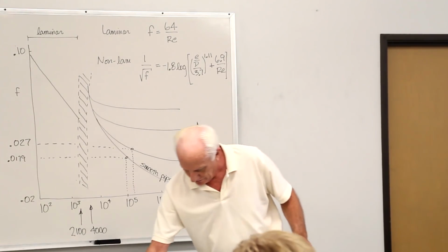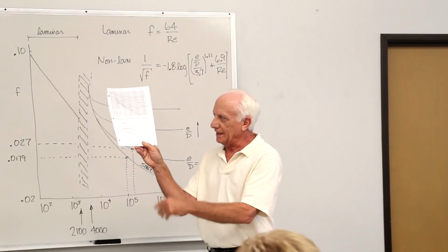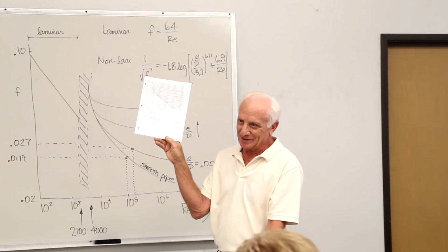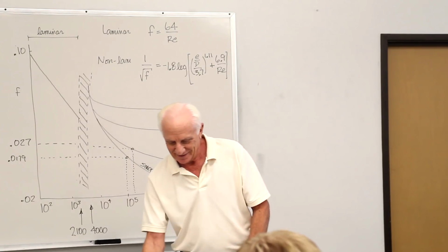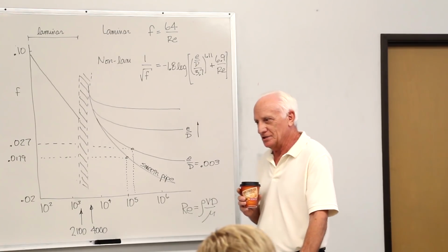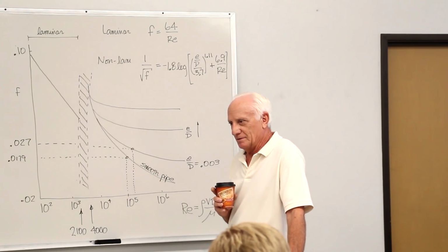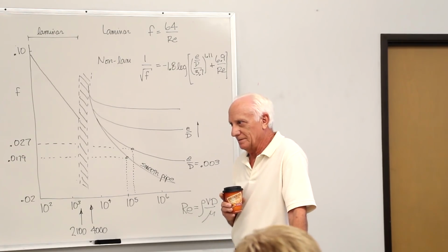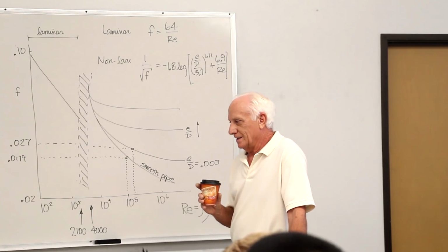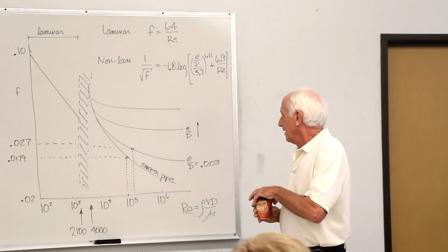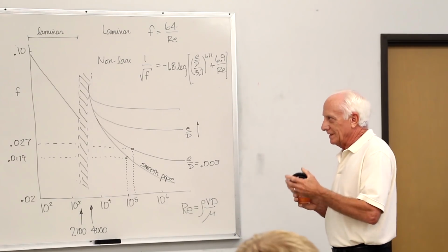And I've given you 3 examples on the handout of how to find F. So you've got tons of examples on how to find F for a particular fluid, a particular pipe, a particular geometry. Geometry is the diameter. The fluid is kinematic viscosity. The kinematics is the velocity. So velocity, diameter, and the properties of the fluid. Okay, so that's how you can use that.